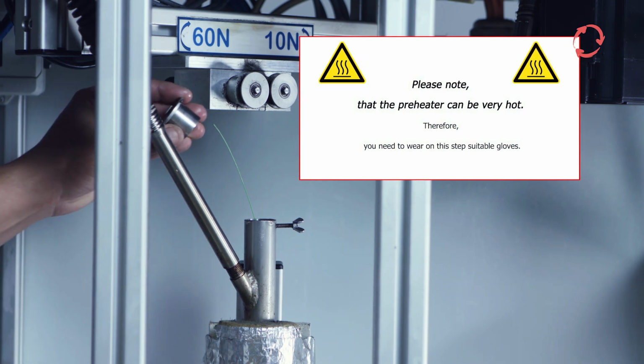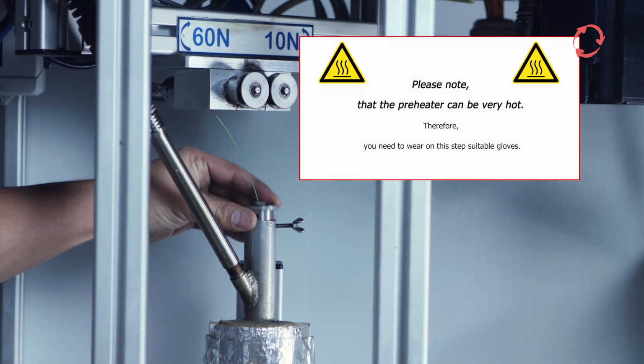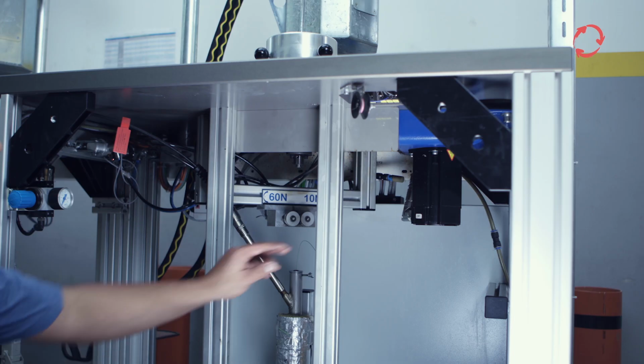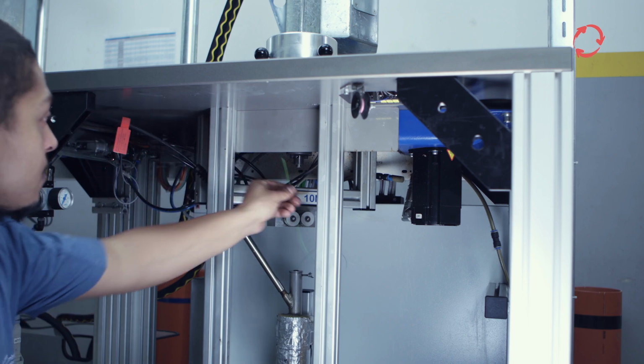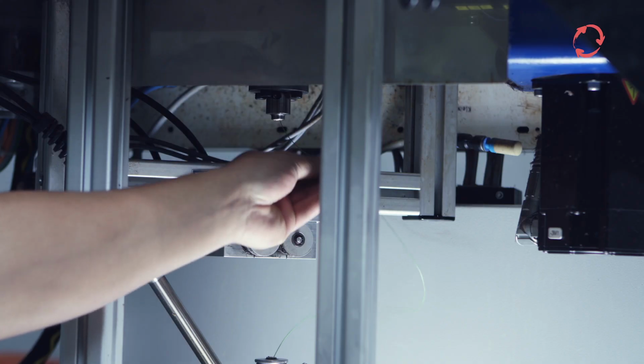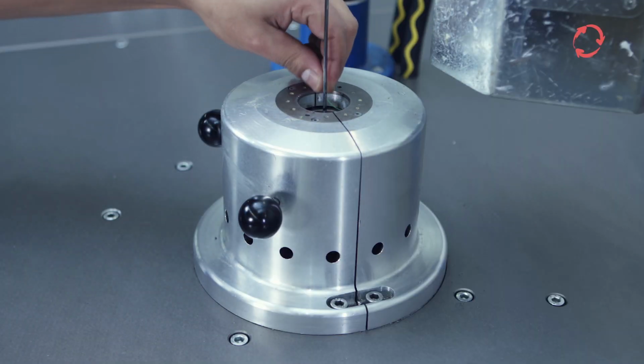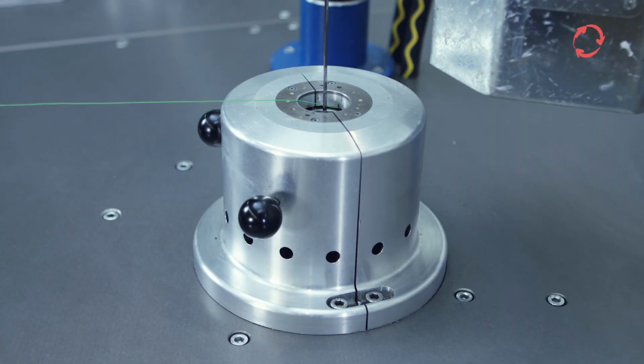Please note, the thread must also be guided through the lid, then retighten the thumb screw. After the thread has exited the preheater, it is guided over the thread tension sensor roller to the winding head. Push the thread through until it comes out of the winding head at the top.